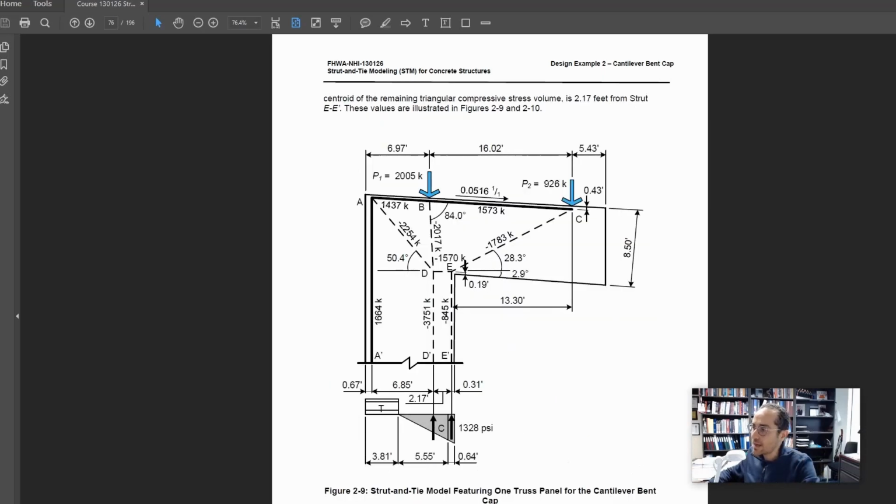As you can see, he is creating two struts for this situation to not exceed the concrete capacity. Tension, you don't need that. Tension is neglected. He's not even showing the stress distribution for tension, because in tension we neglect it, there is no concrete, it's just a rebar. So he's putting the rebar at a certain distance, which also needs to be determined. So the challenge comes from this situation.